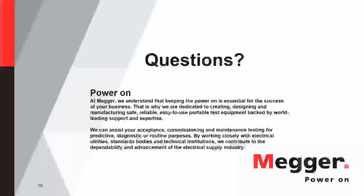If I'm a manufacturer and I have my ISO certifications and all that, they'll generally try and calibrate their transducers once a year. But as far as field goes, I don't see as many people calibrating them that often, and there's no quite standard telling you should calibrate these things once a year. Because generally you'll look at the measurement and you'll see, hey, this is what I'm expecting or what I'm not. And what's nice is you're measuring your times, your strokes, your velocities, and all that. So if everything's in match, you know that your transducer's calibrated and working well.